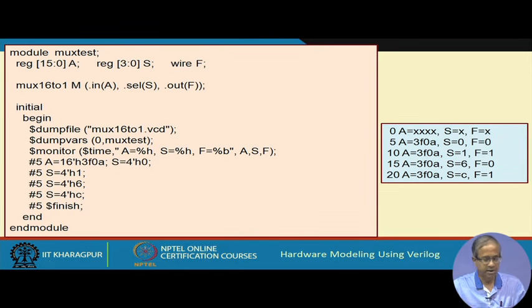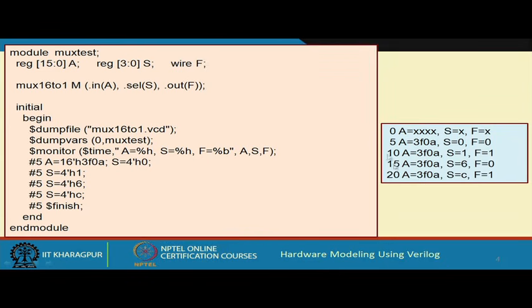So, if I create these two files, and I told you earlier that you can use any of the simulators to simulate these, and I had suggested using Icarus Verilog, which is very easy and freely available. In the examples that I am showing, I have used Icarus Verilog and GTKWave to show you the simulation outputs. If I simulate it using Icarus Verilog, I get an output as shown in the window here, this blue box.